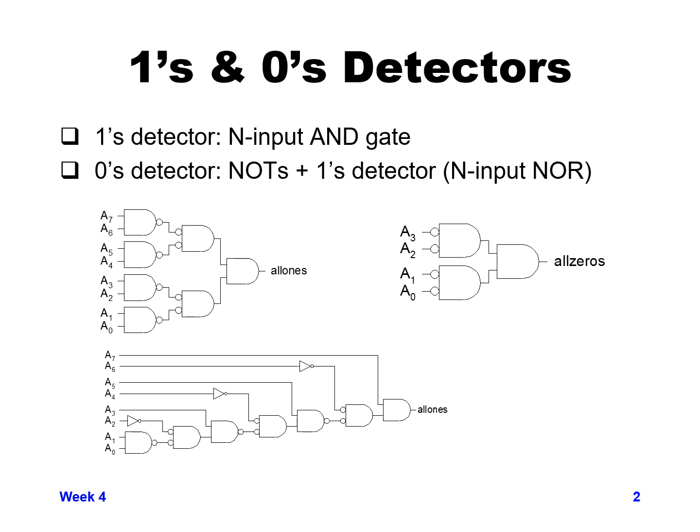Now you could create an 8-bit AND gate that's a single NAND function, but that would require 8 series transistors in a single stage, which typically is not something you want to do in modern process designs, because the delay through 8 series transistors can get prohibitive and actually be worse than the design shown here, where you can take a NAND gate followed by a NOR gate, which you can think of as effectively a not AND gate.